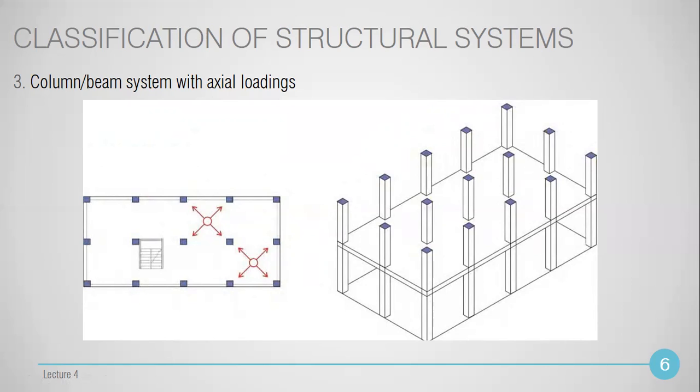In this system, the dimension of vertical elements is extremely reduced, and these vertical bearing columns are instead at the intersection points of the constructive grid in order to transport axial loadings to the ground. Then these points are connected with the horizontal elements, beams, and the end of it functions as a frame.